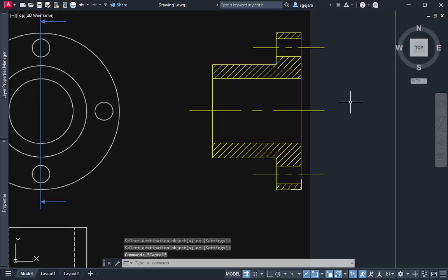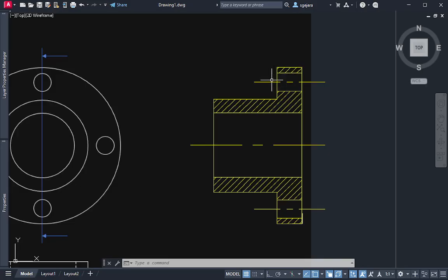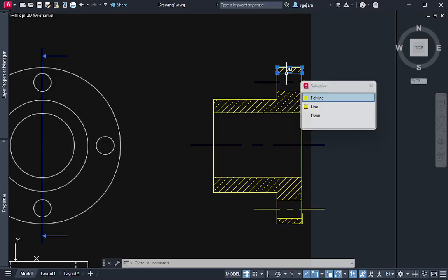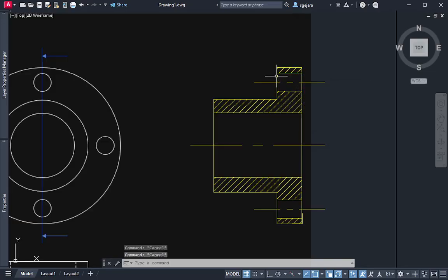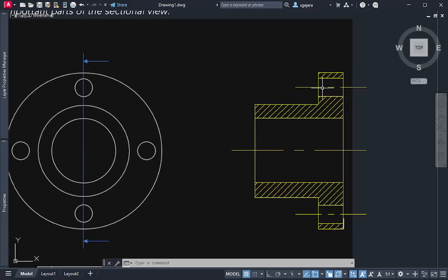Okay? So again, importante ito class, no? The center lines are important because it shows you na curved yung surface. Kasi if there were no center lines here, pwede mo i-argue na baka hindi to curved na surface. Baka pwedeng i-argue na yung nandito is actually a square na hole siya. Tama? Pero we know, based on this drawing, that it's a circular hole siya. So kaya siya curved dapat yung surface. And if it's a curved surface, we need to show the center line. Final answer should look like this.